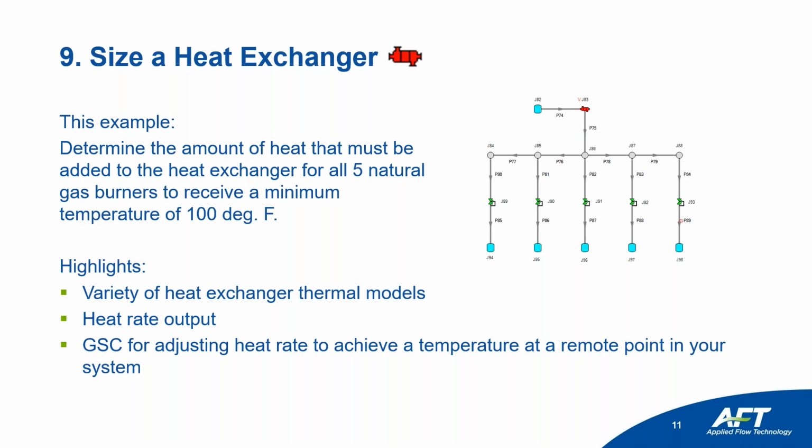But what we need to make sure of is that the gas is reaching each one of these tanks at a minimum temperature of 100 degrees Fahrenheit in order for the process to work properly. And what we're going to be doing is varying the amount of heat that's going into that heat exchanger at the top in order to achieve that outlet temperature.